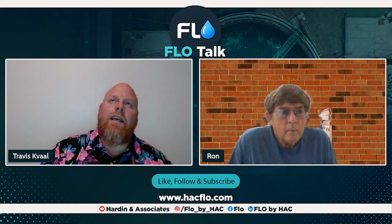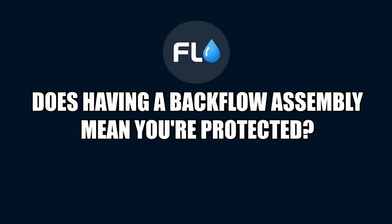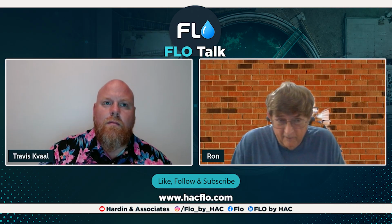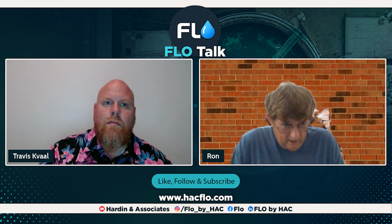So again, if I'm a facility and I have a backflow assembly installed, does that automatically mean I'm protected? Absolutely not. It depends on the health hazards there. It depends on whether it was tested. It depends on what backflow assembly we have. And it depends on whether any changes or modifications were made to the facility. There's a lot of factors there.